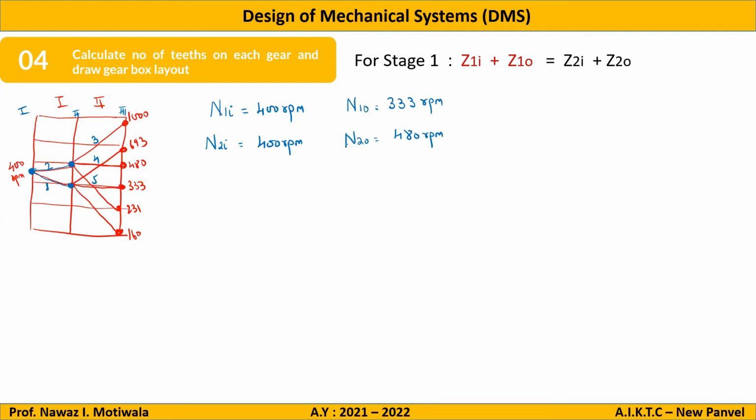Now, is it our requirement? हमको speed चाहिए कि हमको number of teeth चाहिए अभी? Number of teeth चाहिए, sir. So now can you recall what is the relation between number of teeth and the speed? Come on. वापस से MD2 में पढ़ चुके हो. N2 by N1 is equal to T1 by T2. Correct. Or I can say there is an inverse relation. If number of teeth goes on increasing, RPM goes on decreasing. Are you with me? Yes, sir.